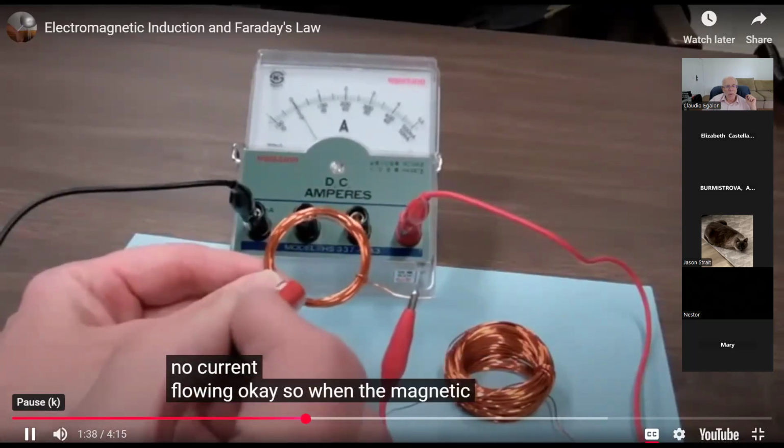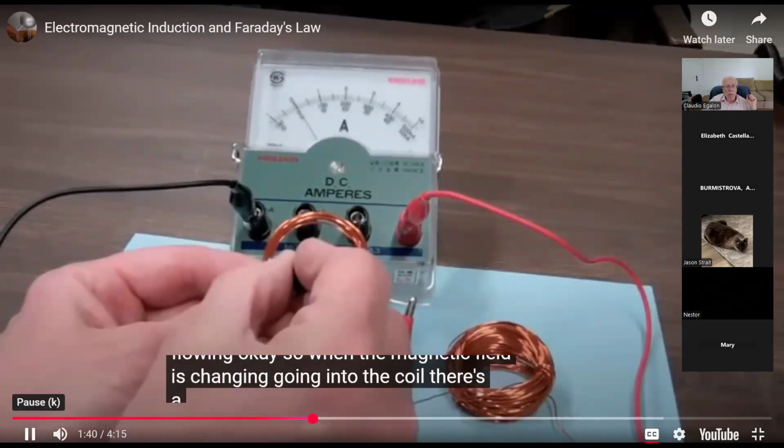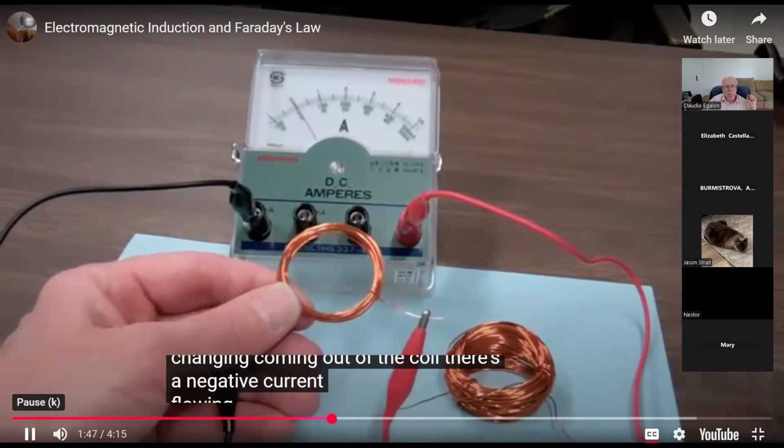So that's how you change the magnitude of the magnetic field, by moving the magnet closer and further away from the circuit, okay? When the field is changing going into the coil, there's a positive current flowing. When it's changing coming out of the coil, there's a negative current flowing.